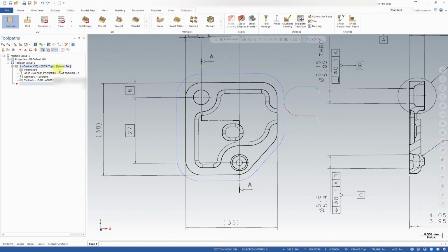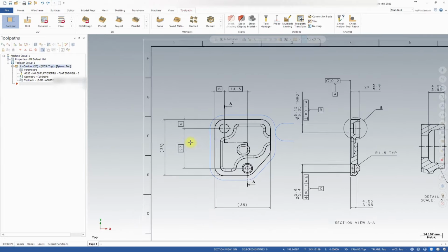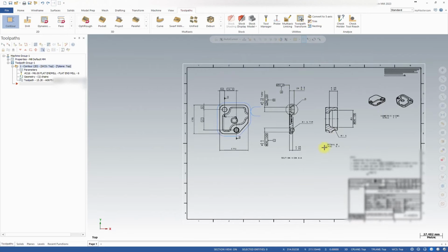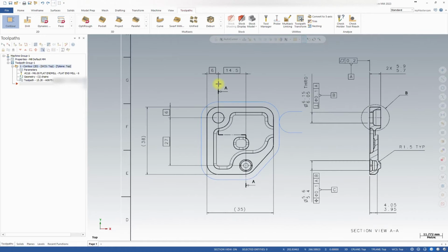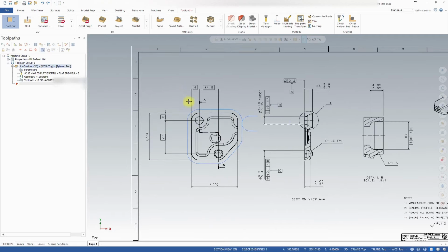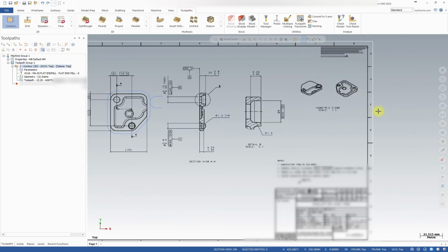And sometimes you get the job to program without the 3D model. The customer doesn't have a 3D model, and you have to draw everything yourself. Sometimes you have to create the 3D model yourself. In this way, you can just open PDF in Mastercam. You can measure missing sizes, and yeah, that's great. I think it is really good option, and it is worth playing with. Of course, we need to remember to scale the size to the proper dimensions. You know, measure the dimension and make sure that it's all good.